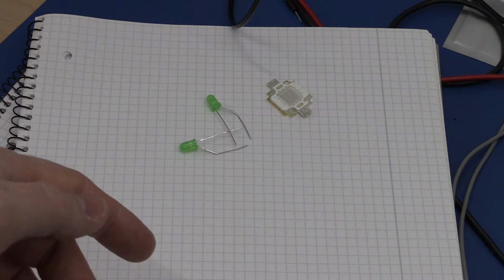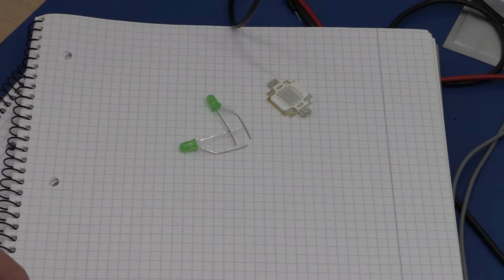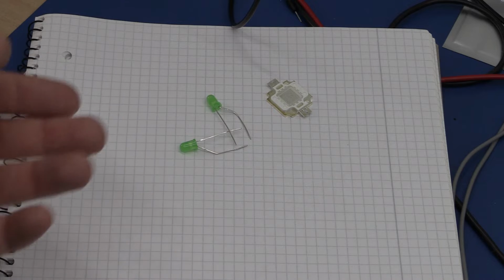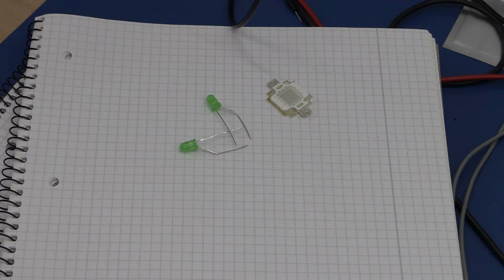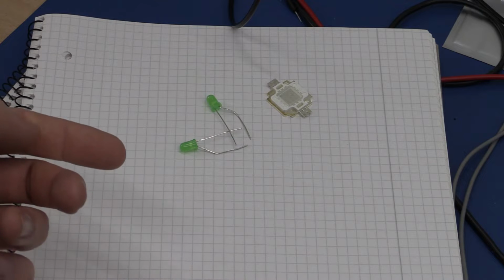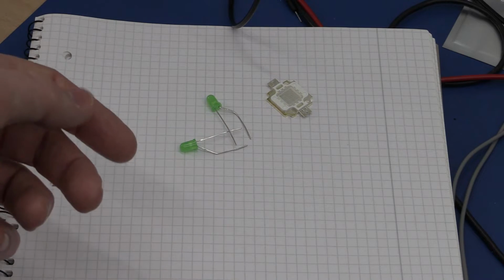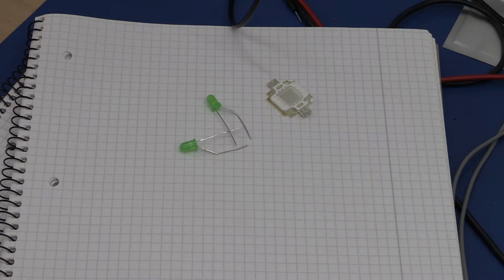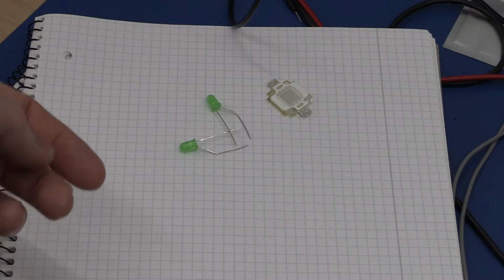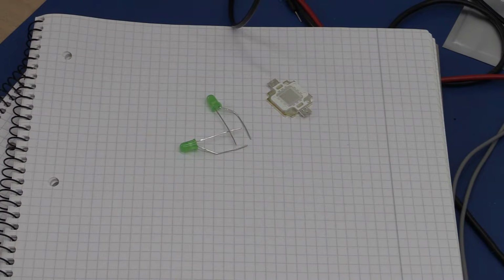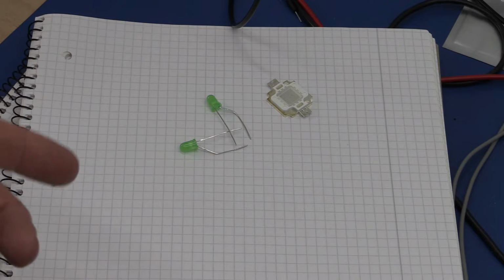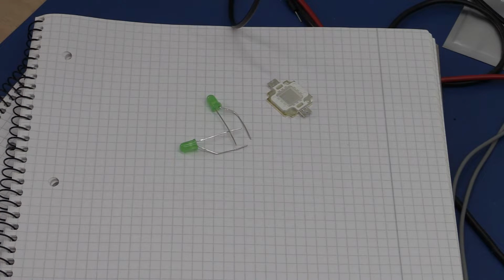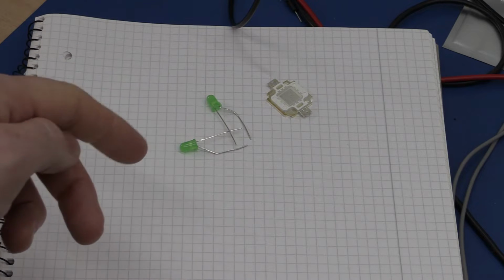It doesn't really make sense to build one yourself, but it's still good to explore the theory and understand how it works. For the linear current sources or sinks, it can make sense to use discrete components and make it yourself, but not really for the switching. It will end up costing you more than the IC, and you will probably not get it as stable as a board IC. Of course there's many ways to make a switching regulator, but I think in this video we will just look at probably the simplest one that still uses PWM.